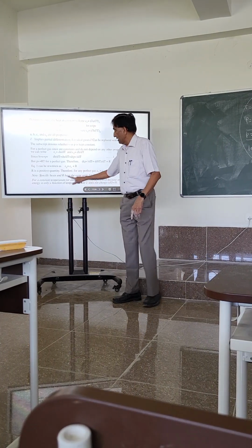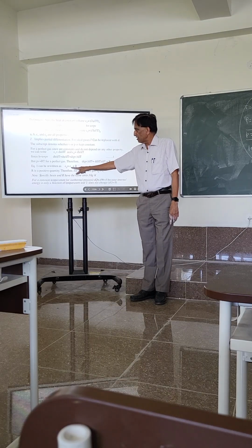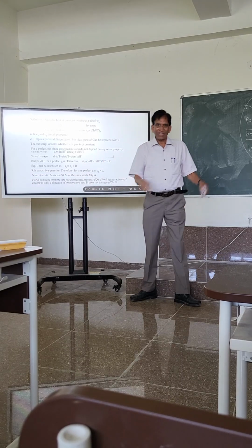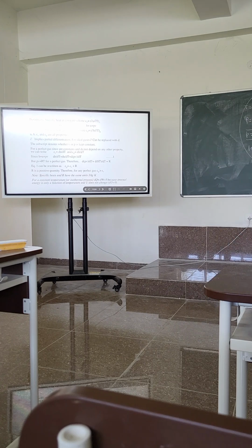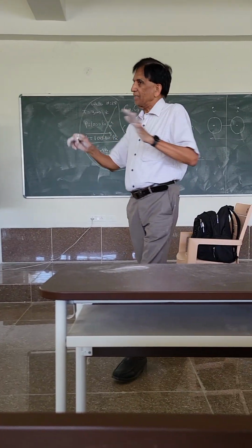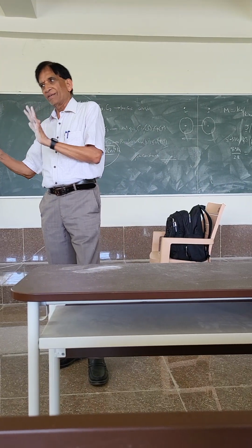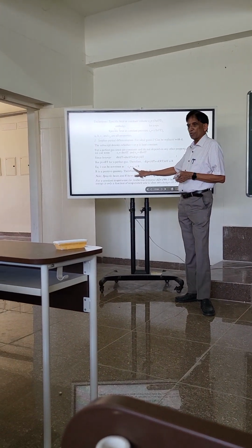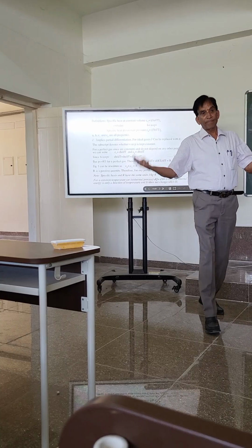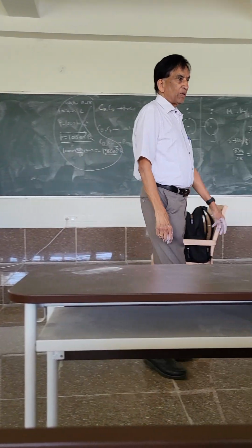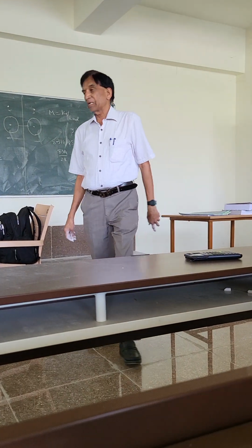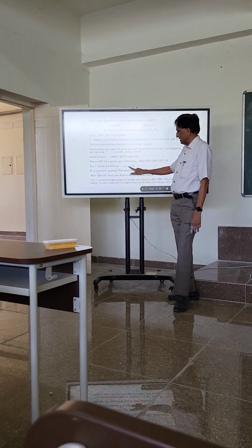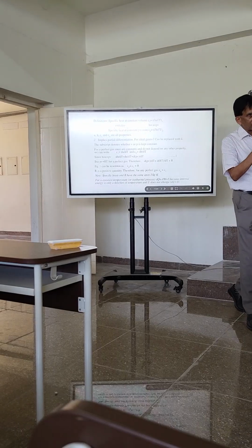Okay, that is for an ideal gas, because here we are substituting Pv equal to RT. So specific heat at constant pressure is equal to specific heat at constant volume plus the gas constant. Use consistent units. If I am using joules per kg Kelvin, it will be that for all three. If it is joules per mole Kelvin, Cp, Cv and R will all be in joules per mole Kelvin, or kilojoules per kilomole Kelvin. Or if you want to use a mass basis, these can be joules per kg Kelvin. As long as the units are consistent.